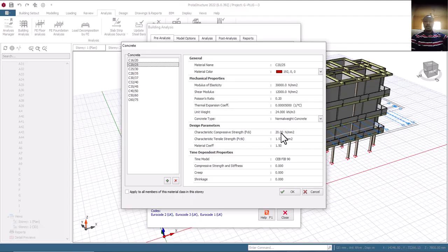You have to come here. Can you see it now? If I click on the first one, can you see it's telling me I'm using grade 16? And if I'm using grade 16, the weaker your concrete, the bigger your section is going to be to withstand the load. Are you getting it? So the stronger your concrete, the smaller the section of a member. So at least with this grade, understand the mixing ratio that gives you this grade is a good one. We have to do something that is obtainable, that will not break the client's back. You understand what I mean in terms of expenses.